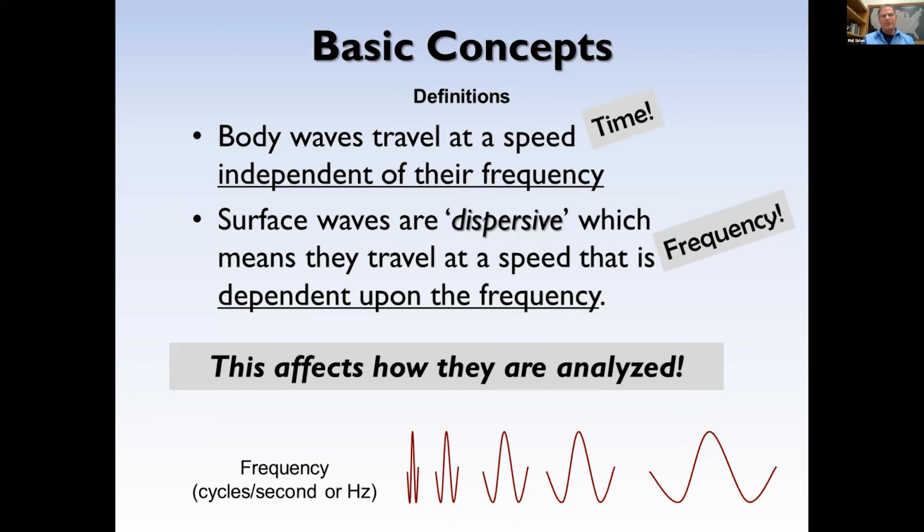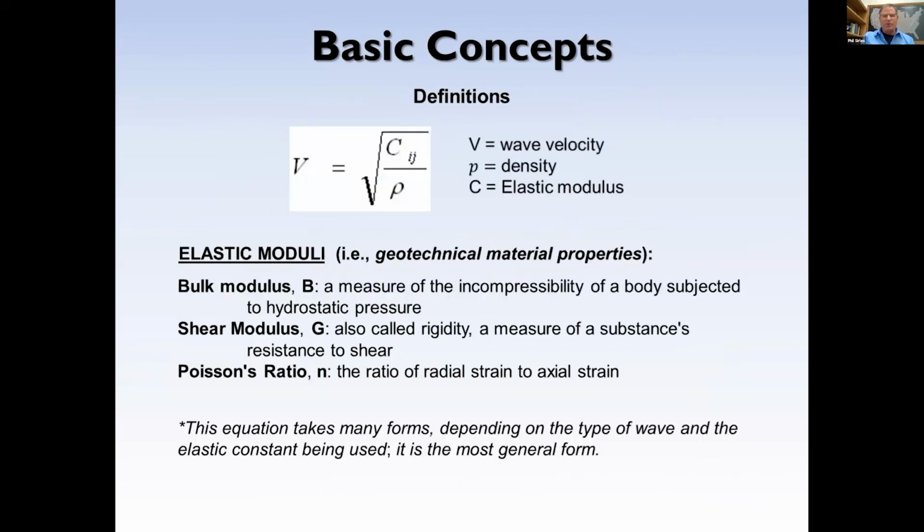So very quickly in seismic, we start to have to analyze our data differently, in the sense that we're either going to analyze it in terms of time, if you're talking P and S waves in the body wave world, or S waves, Rayleigh waves and Love waves in the world of surface waves. So understanding that, you'll see today in the presentation I put a graphic at the bottom of the screen, just so that visually you can see what a high frequency or a low frequency might be, as those waves look on the screen.